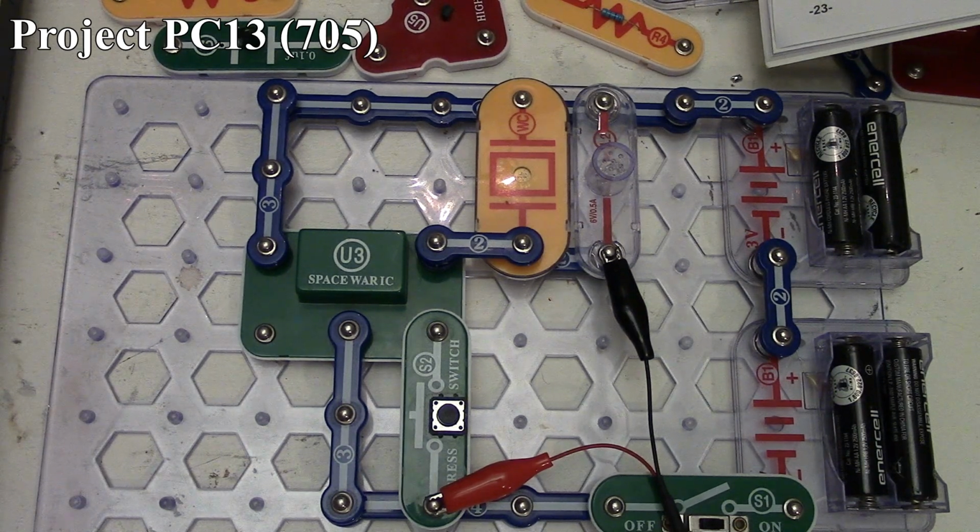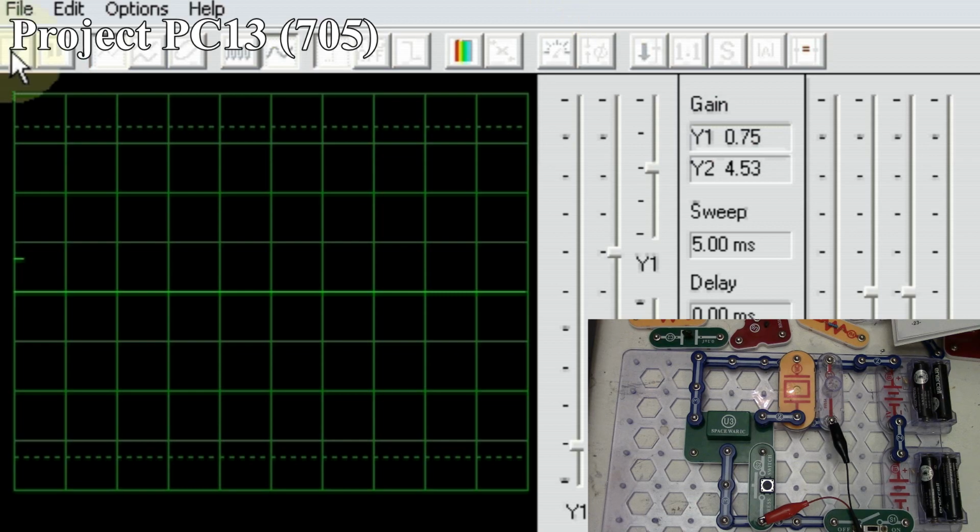So let me get Cam Studio recording our oscilloscope here. Okay, and get the scope recording. As we cycle through the sounds, we will get different waveforms on the oscilloscope, and I've already preset it with the trigger and half millisecond division and all that stuff, so we can see what it does.